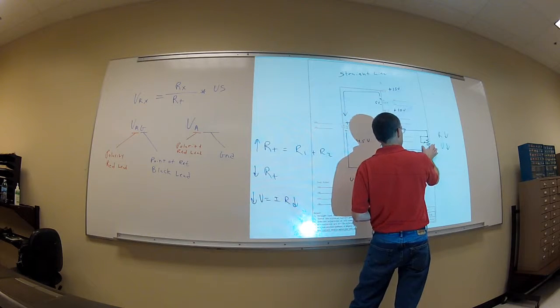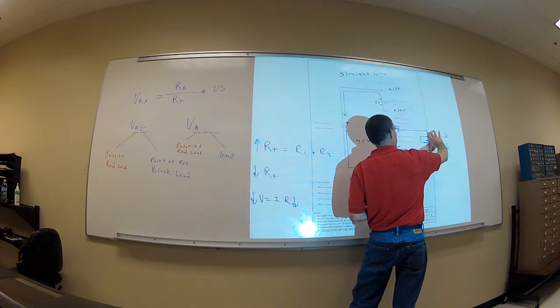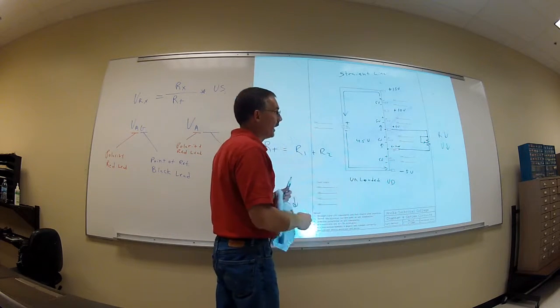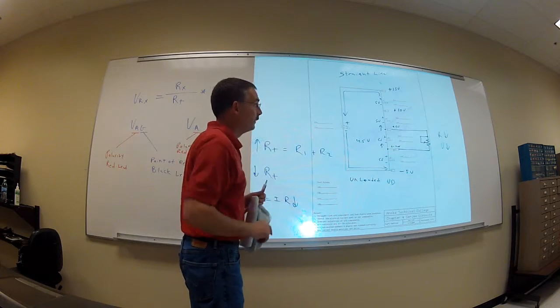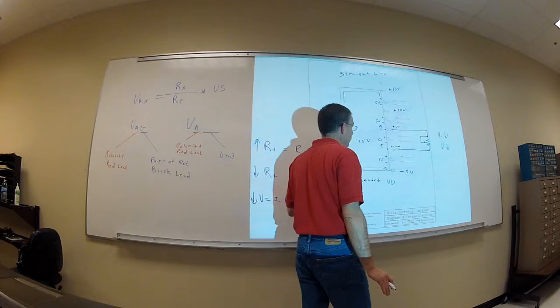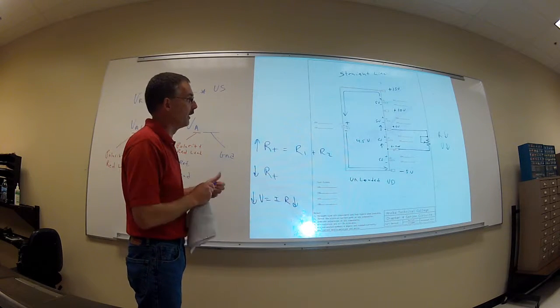Once you drop it down to that 10% value, turn your power off, remove your potentiometer from the circuit, and measure what that resistance was. And that'll tell you what your resistance was. That will tell you how much you loaded that circuit down. Okay? So they're kind of getting you going already for chapter 6 in that further investigation.